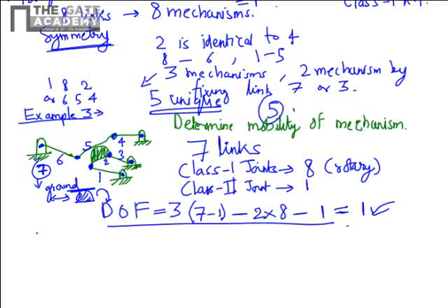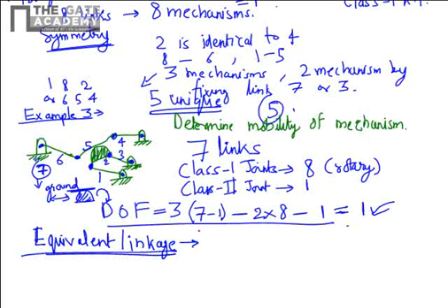Now while solving this example, you have come across a joint of CAM. So we know the degree of freedom of a CAM mechanism. In some cases, such as for testing the aptitude, you will be given some different kind of element in the mechanism, such as a spring or a sliding joint or a CAM. In those cases, we have a powerful concept called equivalent linkage that can be used to simplify the problem. So I'll just illustrate that example for you.